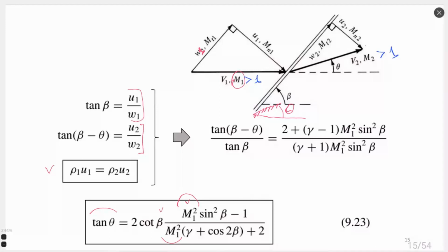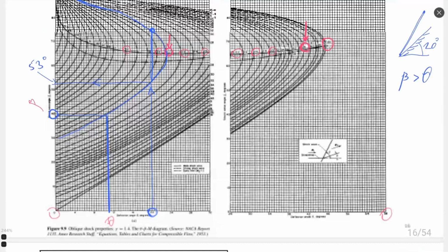You need to find an error. Oblique shockwave theory says, and not just theory but also real life says, that flow remains supersonic after an oblique shockwave, which is completely different from a normal shockwave. In the normal shockwave, flow is supersonic before the shockwave and subsonic after the shockwave. So pay attention to this.